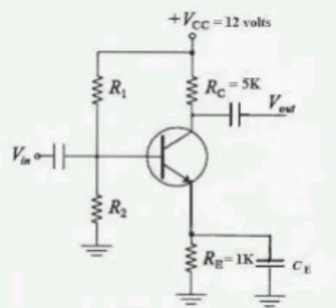Design a Widlar current source shown in the figure below to give I naught equal to 5 microamps and IR equal to 1 milliamp. The parameters are VCC equal to 30 volts, VBE1 equal to 0.7 volts, VT equal to 26 millivolts, beta F equal to 100.